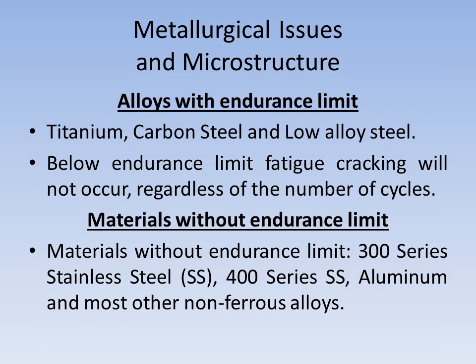Alloys with endurance limit are titanium, carbon steel and low alloy steel. Remember, below the endurance limit, fatigue cracking will not occur regardless of the number of cycles. Materials without endurance limit are 300 series stainless steel, 400 series stainless steel, aluminum and most other non-ferrous alloys. This we have to remember: materials with endurance limit and materials without endurance limit.